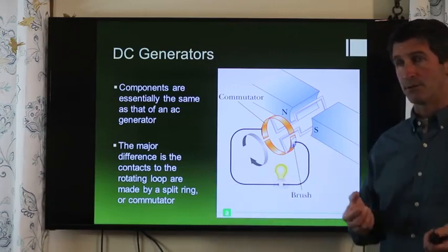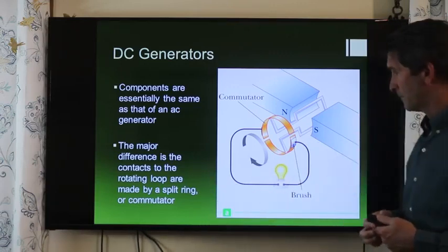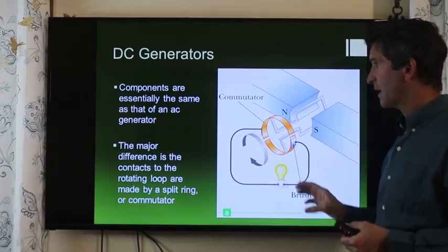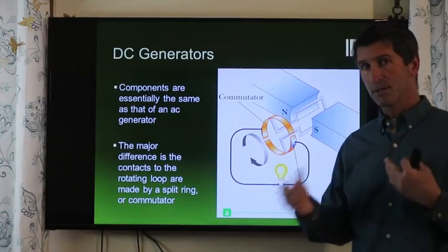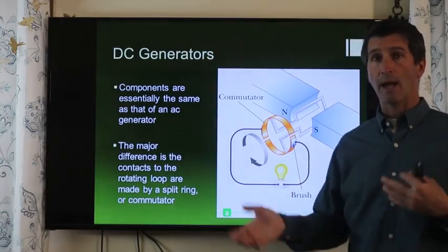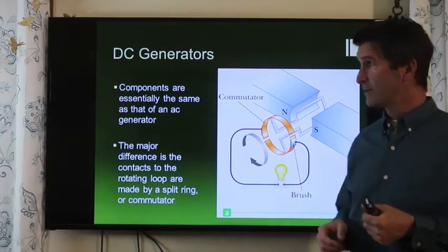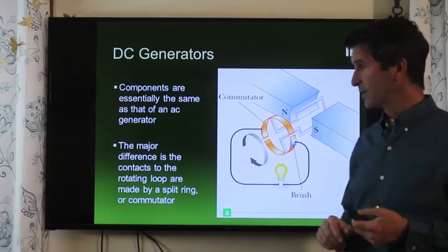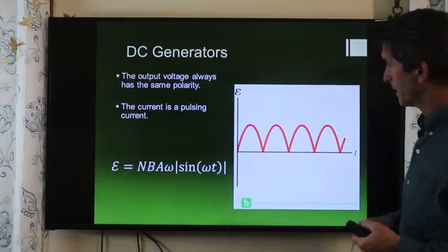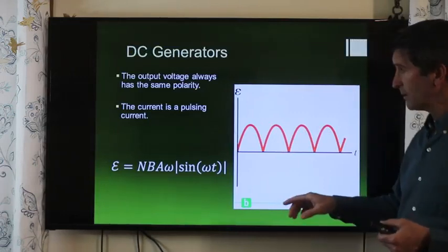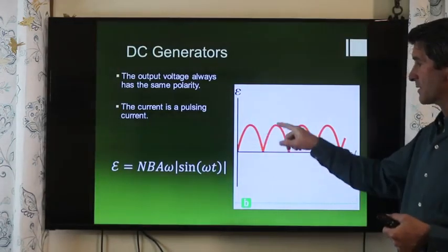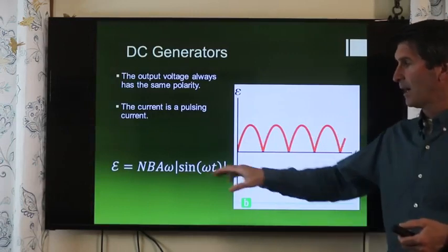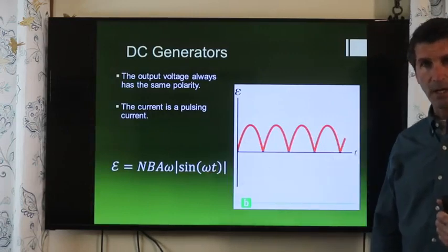If you get mechanical energy out of it, it is a motor. Now, the interesting thing here is, even with the commutator, we're still going to get current flowing only in one way, as we needed for the DC motor. However, we're not going to get a constant voltage here. If we look at the voltage coming out of here, the split ring commutator actually causes it to increase and decrease by the absolute value of sine.